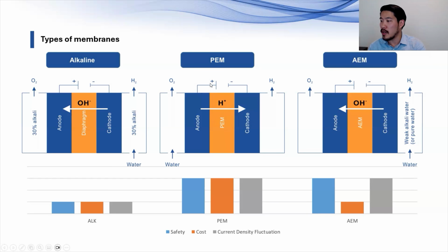It goes through as a proton, and then the electron goes through on the other curve, and then comes through on the other side as hydrogen here. So here there's a lot of pressure buildup with the hydrogen, but with the newer technologies, we're able to adjust the pore size of the exchange membranes to the nano size so that you're able to prevent hydrogen from crossing back over from all the pressure buildup.